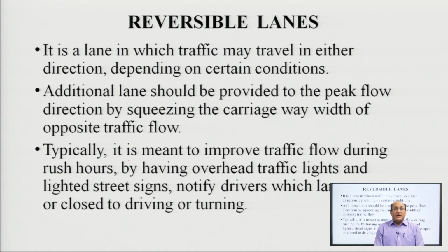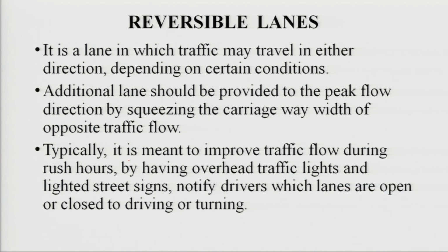Reversible lanes. It is a lane in which traffic may travel in either direction depending on certain conditions. Additional lanes should be provided to the peak flow direction by squeezing the carriageway width of the opposite traffic flow. Typically, it is meant to improve traffic flow during rush hour by having overhead traffic lights and lighted street signs notify drivers which lanes are open or closed for driving or turning.